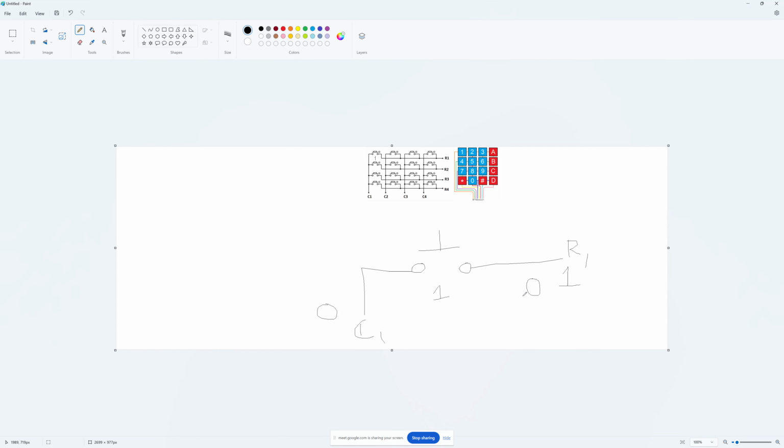So once the microcontroller writes a 1 over here and 0 over here, it will check whether someone is making my pin 0. The microcontroller already wrote 1 over here and it is examining who is making it 0. So if it becomes 0, the microcontroller will understand. This is how they are doing it.